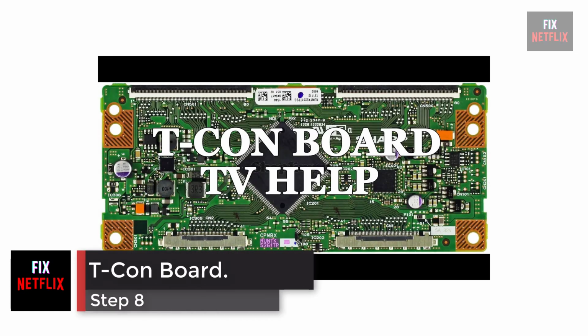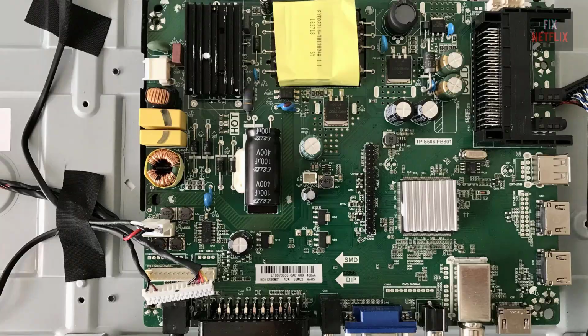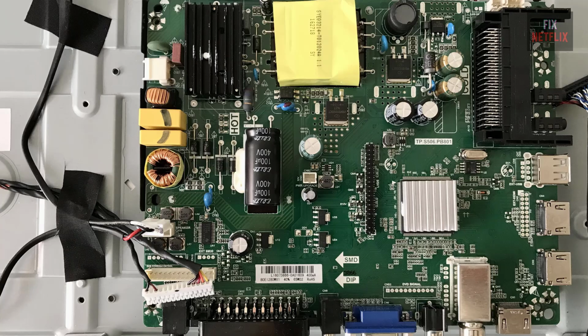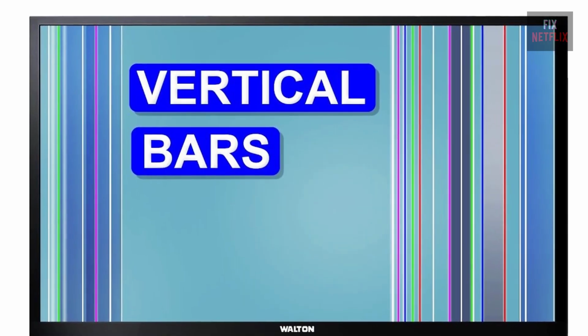Step 8. T-con board. This check for the T-con board also touches on the condition of the main board. Note that problems that show up on half of the screen, like bars or such, point to a failed main board, as the T-con board errors show up on the whole screen. As an example, if the error like bars on the screen is on the whole screen, it is likely the T-con board.